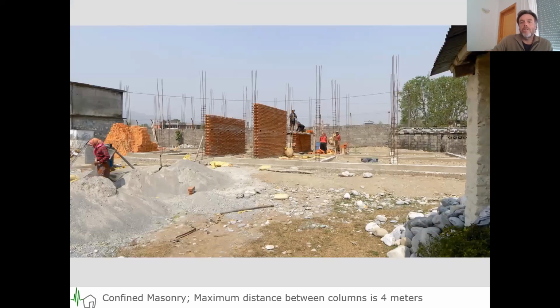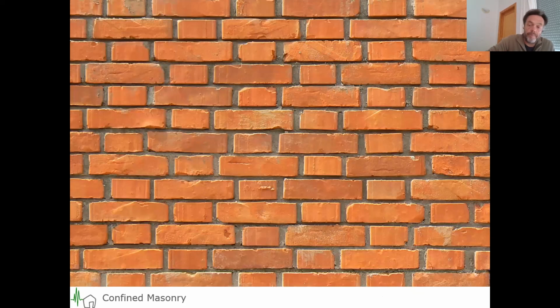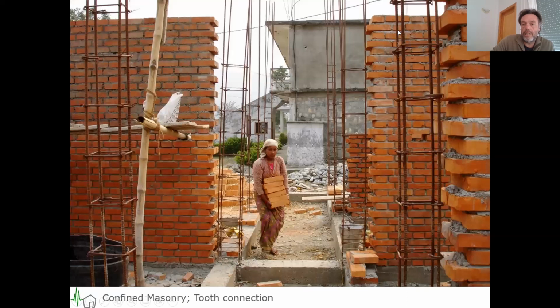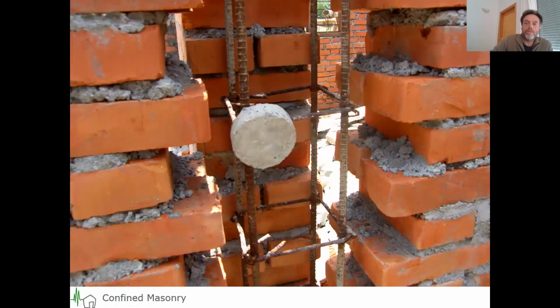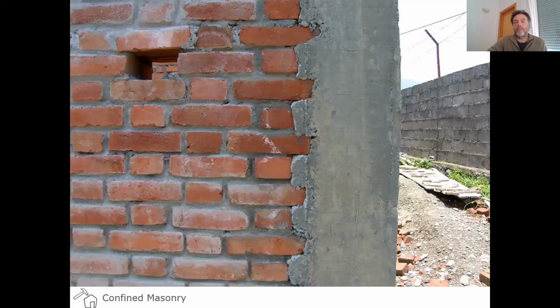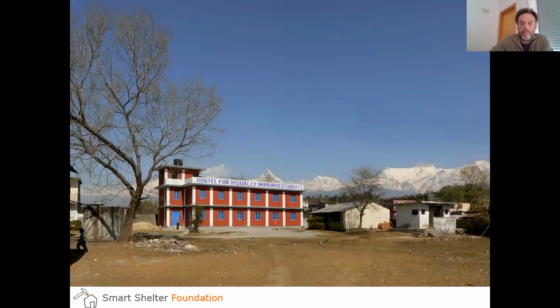That's the first thing. So what you do, you start building your shear panels in between, and it is in a certain pattern. We call it Flemish bond, so that you get a nice tooth at the end. And then what we did, of course, we put in our spaces again. And we cast in the columns like this. And we also show what we do. Take my word for it. We plastered this in the same way so that you still see this tooth pattern.